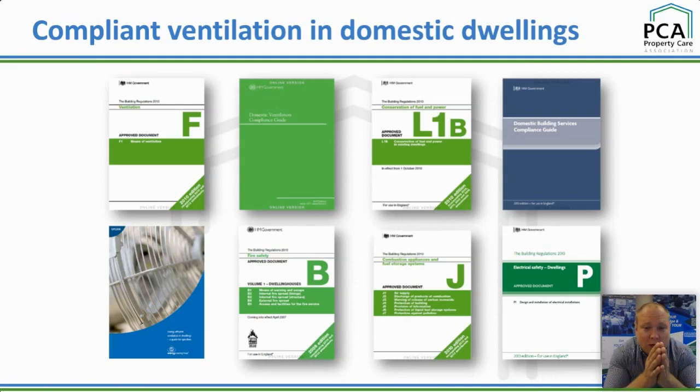But there are other documents as well, and this is the complexity of ventilation that I want to illustrate here. Each of those approved documents being treated in isolation seems to be one of the big problems that come out of the Hackett report and the review of building regs. When you look at ventilation, these are all the documents you will need to consider. You can't just look at Approved Document F in isolation. That's a bit of a caveat, because we are going to look at F in a lot more detail today, but there is more to it.